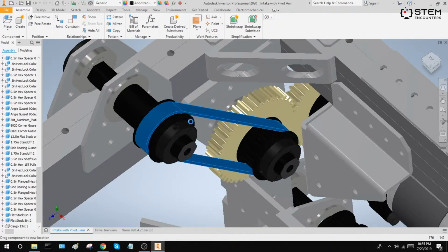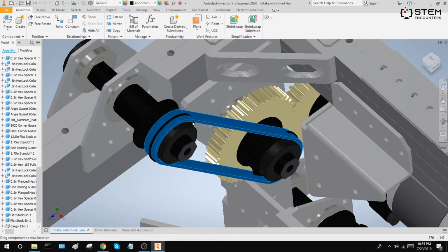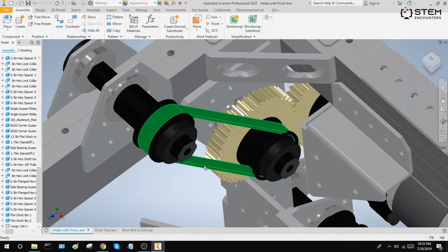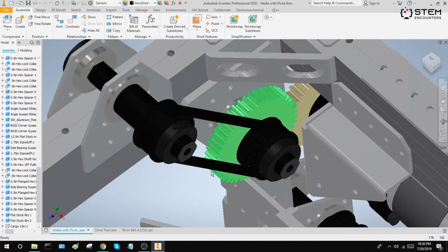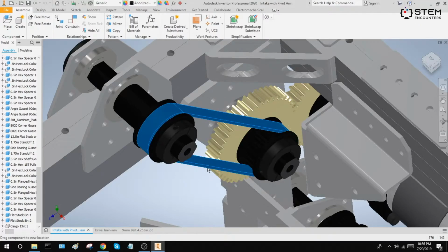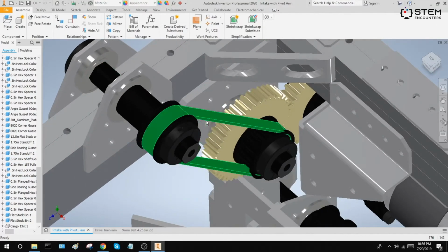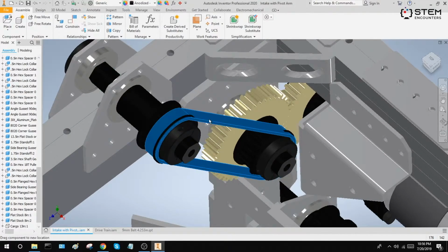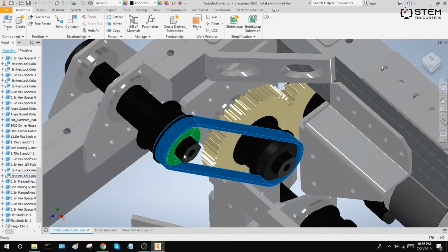For belt and pulley and chain and sprocket setups, it's very difficult to get the exact right length for the chain or the belt because the geometry makes the numbers very long and irrational. So just use a rounded number for your length, then just use a constraint with a maximum to give yourself some leeway so you're not chasing all those digits.